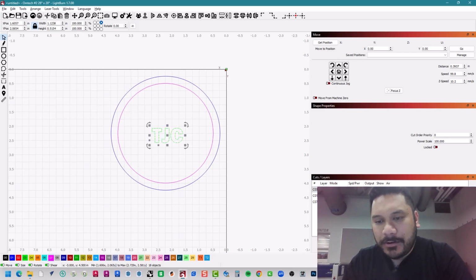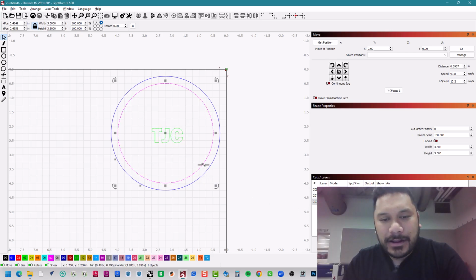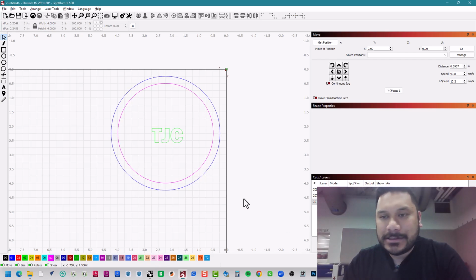So now I am ready to go. I've got my material sitting in the laser. I've got everything turned on as per the handout. I've got the master blower switch. I've got the chiller. I've got the 2 switches on the laser. I've got that gate valve opened. I've got my material sitting on the bed, and it's exactly 19 millimeters away from the laser. I've adjusted the bed to do that.